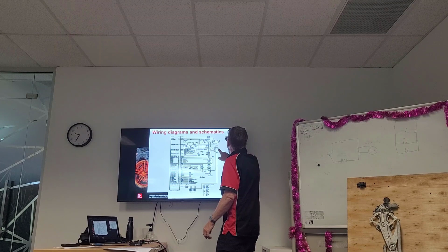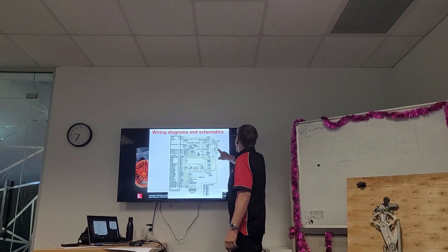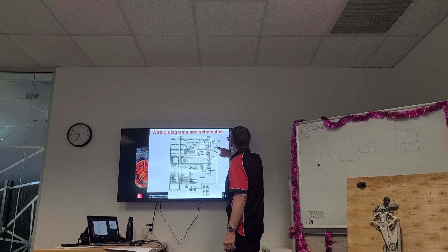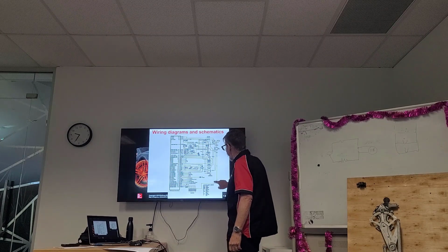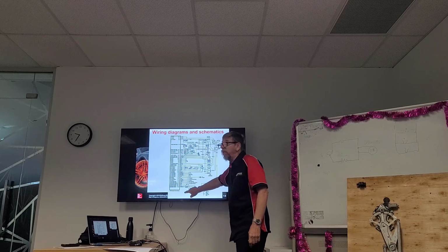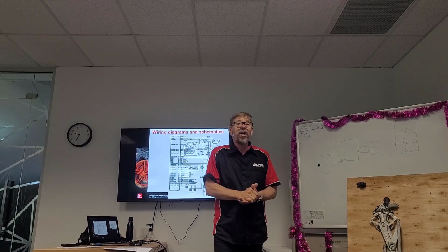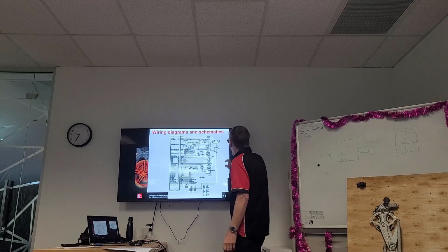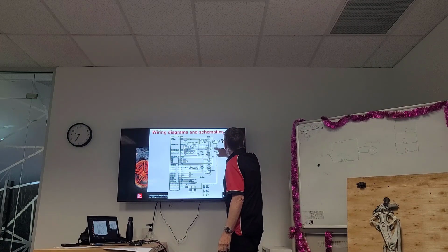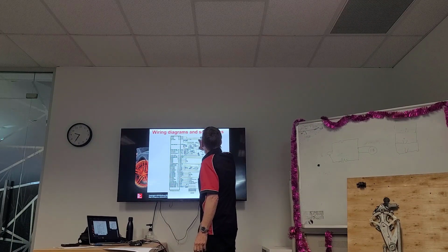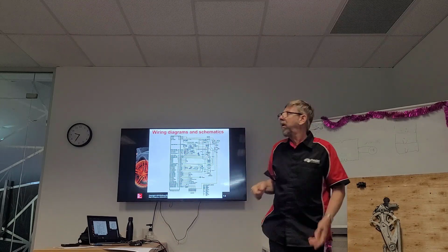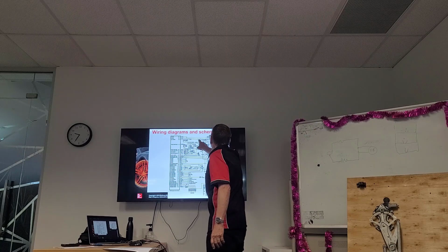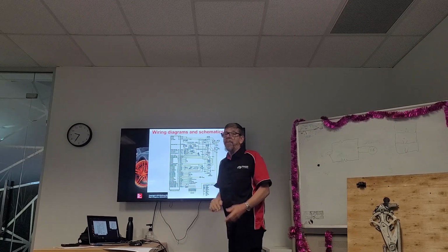If we have a look here, we've got what's called an EFI relay. We can see that switch is open, but if that switch was closed, we can see we get power to what? What's that down there? Injectors. Okay, so here we have a relay. We can see it comes on the ignition side. So when the key's turned on, we now get power to that relay, don't we? Yeah.